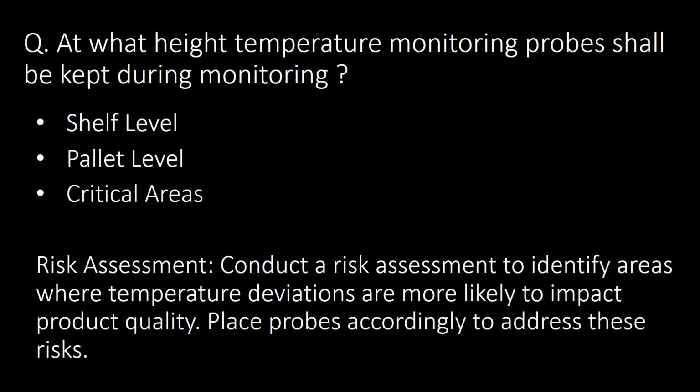This question is more related to the previous one. At what height shall temperature monitoring probes be kept during monitoring? In case of storage areas, they should be kept at various heights like the lower, middle and highest point of shelves. They should be kept at the pallet level also and in critical areas. Ideally, conduct a risk assessment to identify areas where temperature deviations are more likely to impact product quality. Place probes accordingly to address these risks.